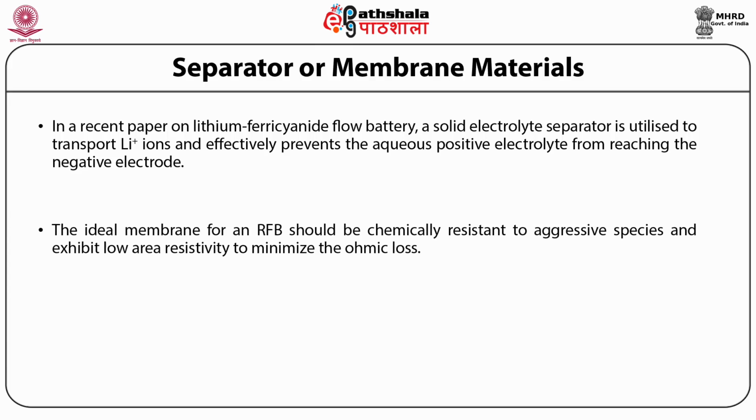The ideal membrane for an RFB should be chemically resistant to aggressive species and exhibit low area resistivity to minimize the ohmic losses.